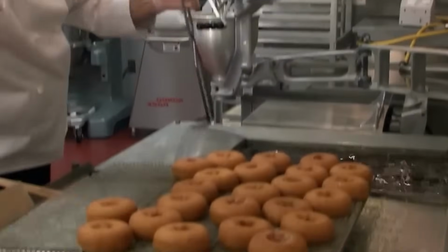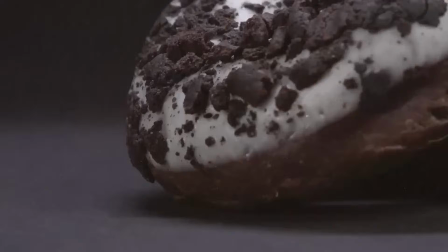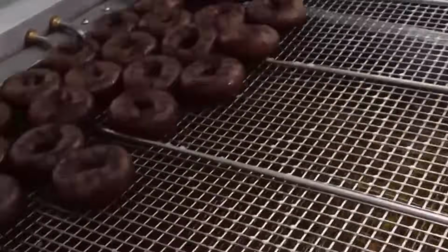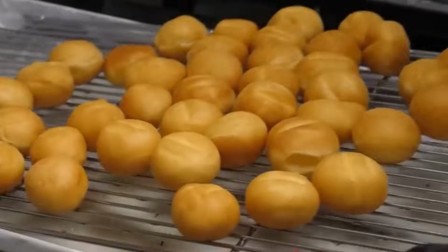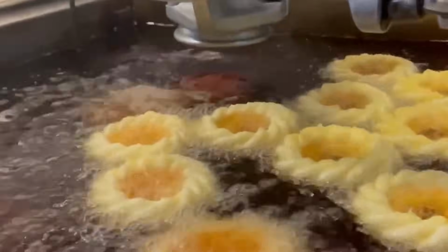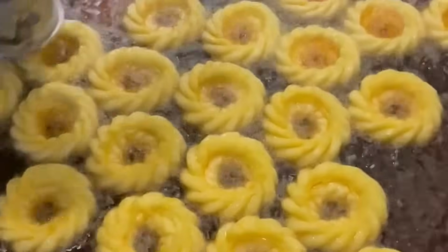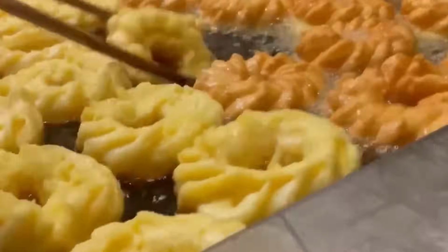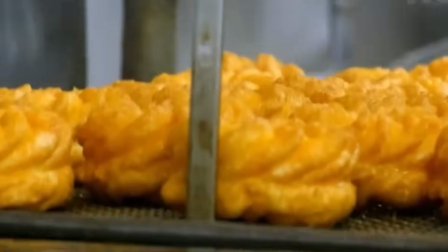Fryer systems include zoned heating elements and oil curtain barriers to minimize heat loss. Oil flow rate and turnover frequency are tracked by volumetric flow meters and recirculation pumps. Air knives at the fryer exit are powered by centrifugal blowers with adjustable nozzles. Their position and pressure are calibrated to strip excess oil without disturbing surface structure or toppings.